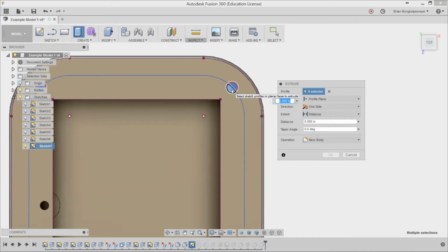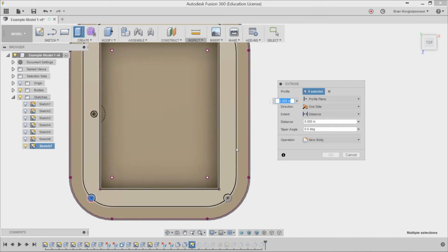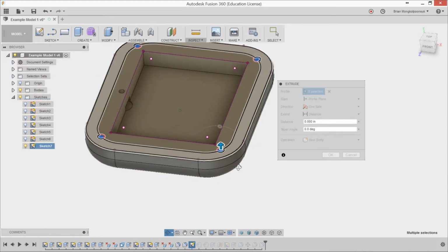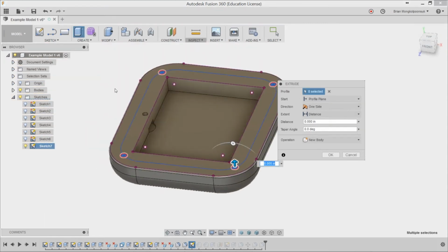This is because, as most of you guys may know, this line in the middle going through it is a normal line. And the best modeling habit for that is actually to make that a construction line. So I had to click 8 times for the 4 different holes, and now I can do my extrusion.